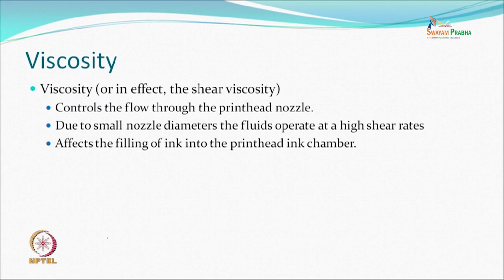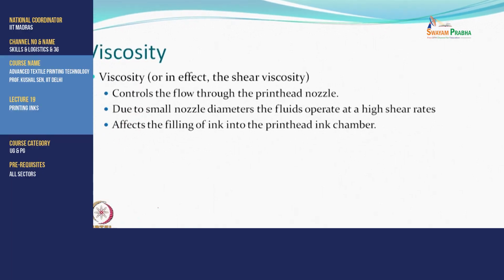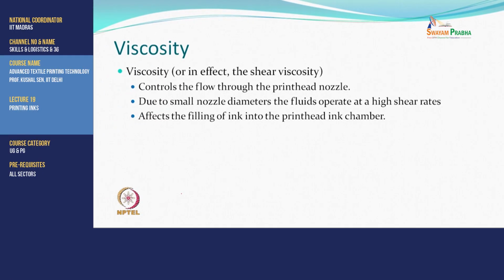Viscosity we just talked about before also. In effect we are talking about the shear viscosity. It controls the flow through the print head nozzle. Due to small nozzle diameters, you can understand so many nozzles are there in a small area. The fluid, while it is coming out, operates at higher shear rates. It affects the filling of the ink into the print head also.